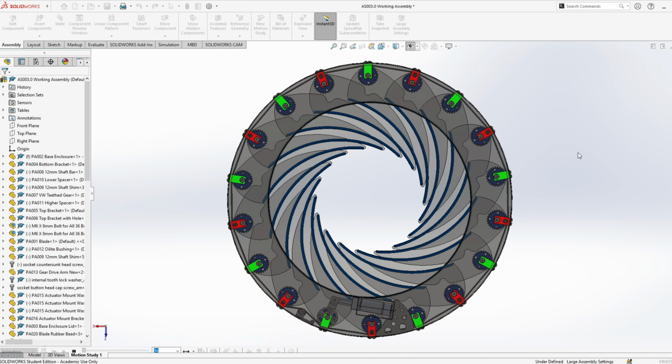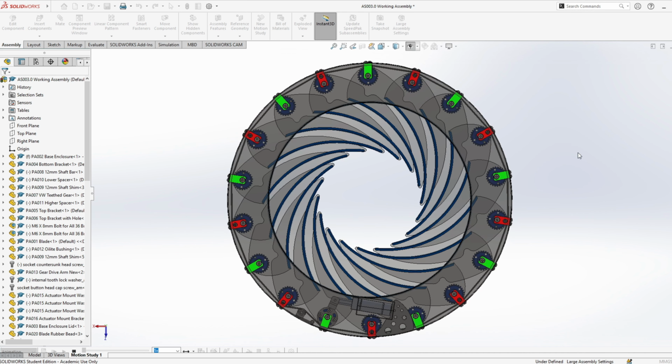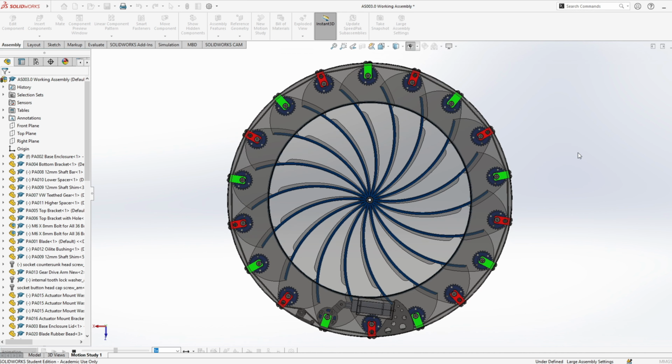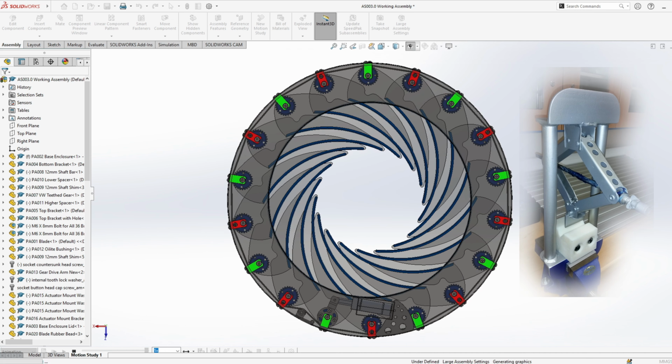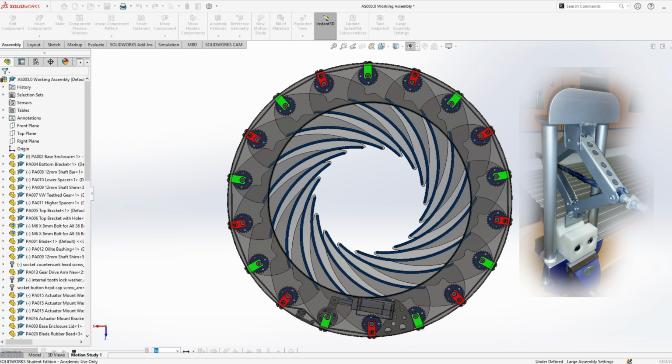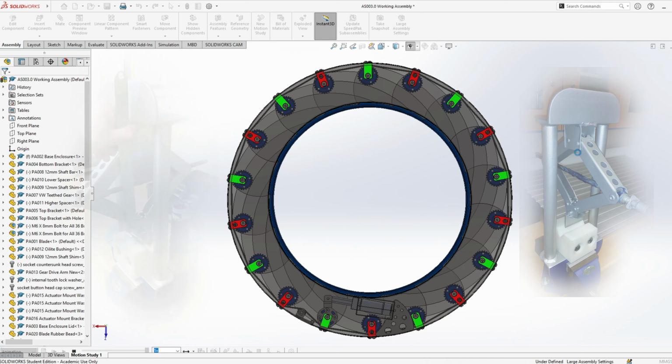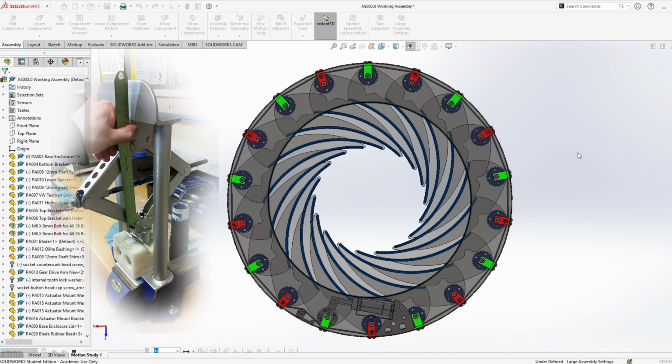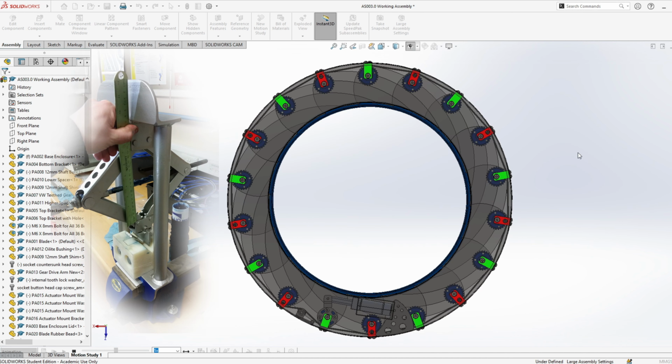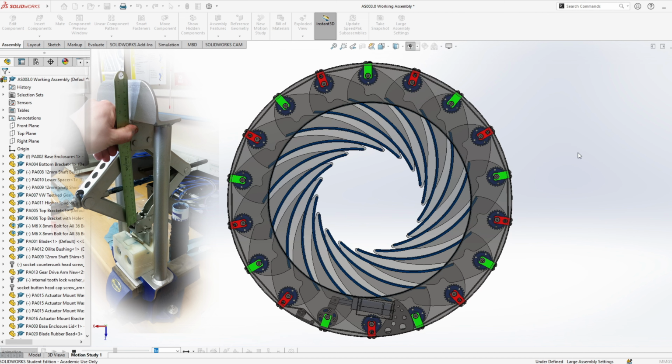Interestingly, these 36 parts were manufactured using a small metal former bender appearing on the screen now. So this device was built specifically for this project with custom V-dies made from nylon blocks to eliminate marking on the mirror polished flat bar whilst forming.